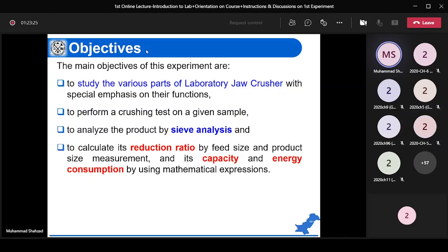Yes, sir. So to measure the performance of a fan, we need to measure the velocity of the air below the fan at different points. For example, the fan is hung on the ceiling and the distance between the floor and the fan wings is about 8 feet. You need to measure the velocity of the air at 6 feet above ground, 4 feet above ground, 2 feet above ground, and at the surface of the ground. So you will measure the velocity at different positions, and then you will compare it to the standards, right?